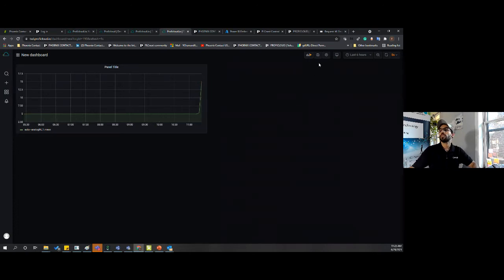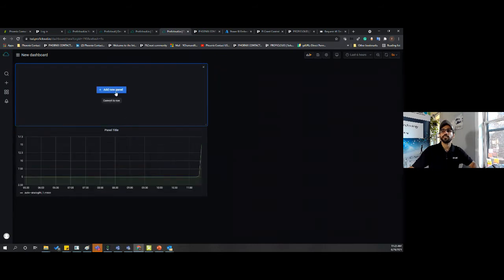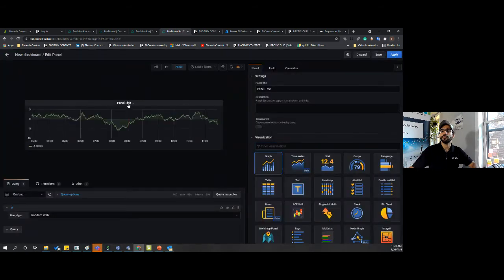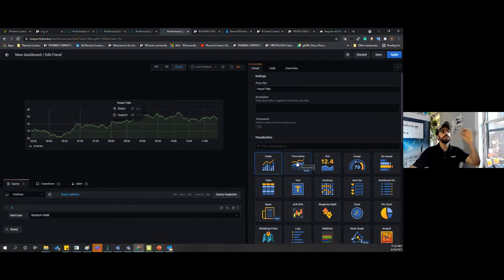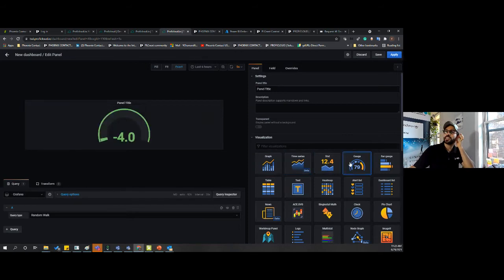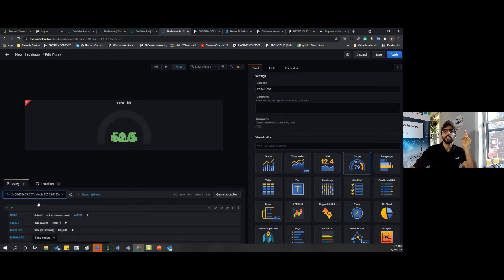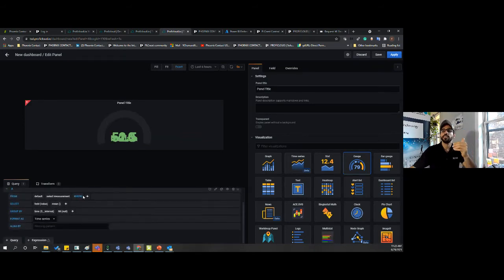So what if I was looking at the data as a single status now? If you wanna, for instance, see the real-time data instead of seeing a historian, you can pick a gauge, right? And you can associate the data the same way I did. You pick your databases, UUID, the UID from the controller, back over here, and we're gonna go for the analog one again.